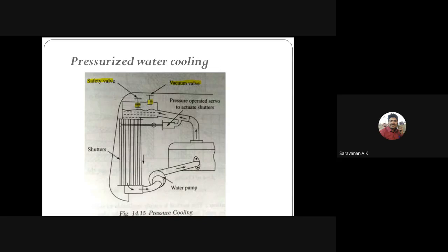When the engine is switched off, the coolant cools down, so a vacuum forms in the cooling system. When the internal pressure falls below atmospheric, the vacuum valve will be opened by the higher outside pressure, and the cooling system then attains atmospheric pressure.